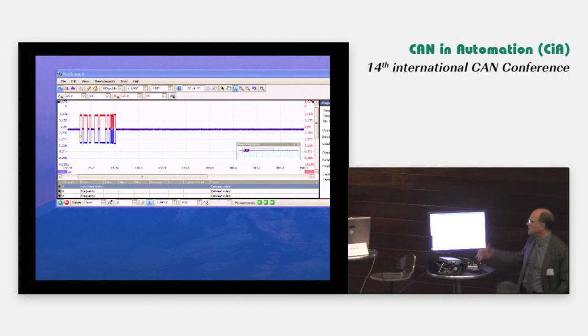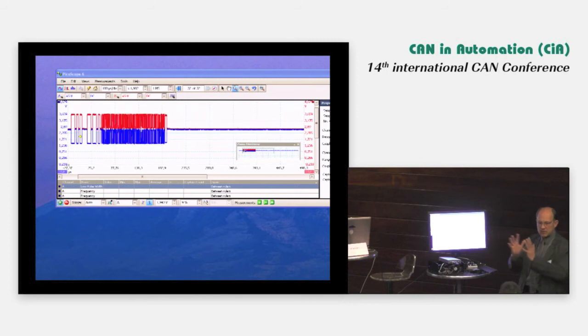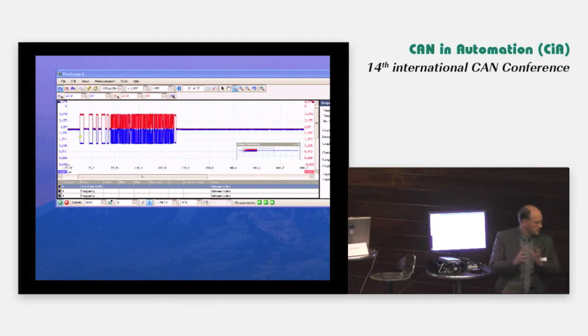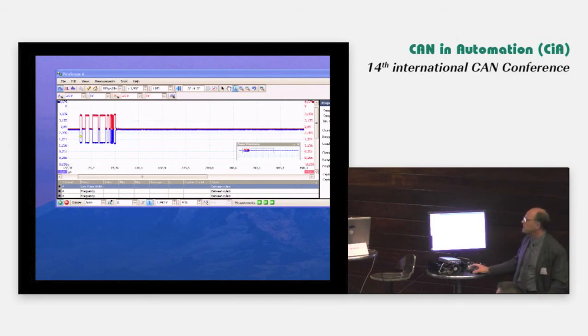This is a system to see how it works, and this is a tool we're using to verify our CAN implementation. We can change both the clock between different modules and also automatically adjust the delay time. So you can check that our solution is robust against different delays. We can synthesize different cabling lengths in the tool, similar to what Unicore is doing with their testing simulation, where we can adjust different things to force different scenarios into the CAN communication.